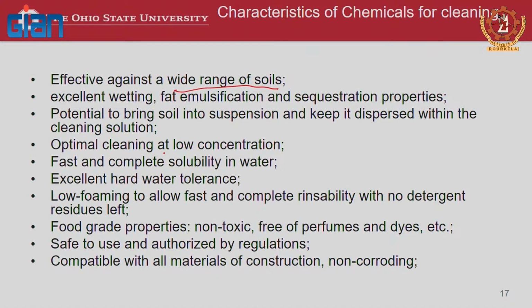And you want to have this done at a low concentration. Especially in the current environment, the food industry is trying to reduce how much chemicals you use for cleaning and sanitation. So, you do not want to use very high concentration, but reasonably low concentration, so that it is still effective in cleaning, but at the same time you are not polluting the environment with a lot of detergents. And water is typically used as the cleaning agent. So, the detergent should be soluble and compatible with that.